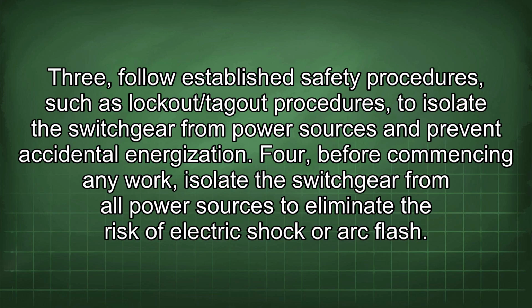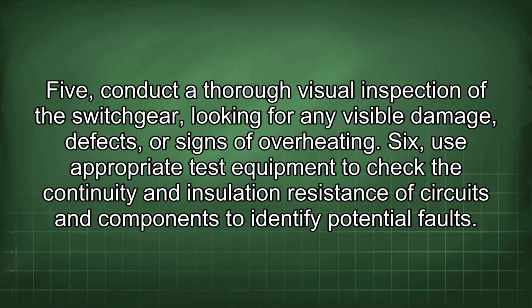4. Before commencing any work, isolate the switchgear from all power sources to eliminate the risk of electric shock or arc flash. 5. Conduct a thorough visual inspection of the switchgear, looking for any visible damage, defects, or signs of overheating. 6. Use appropriate test equipment to check the continuity and insulation resistance of circuits and components to identify potential faults.